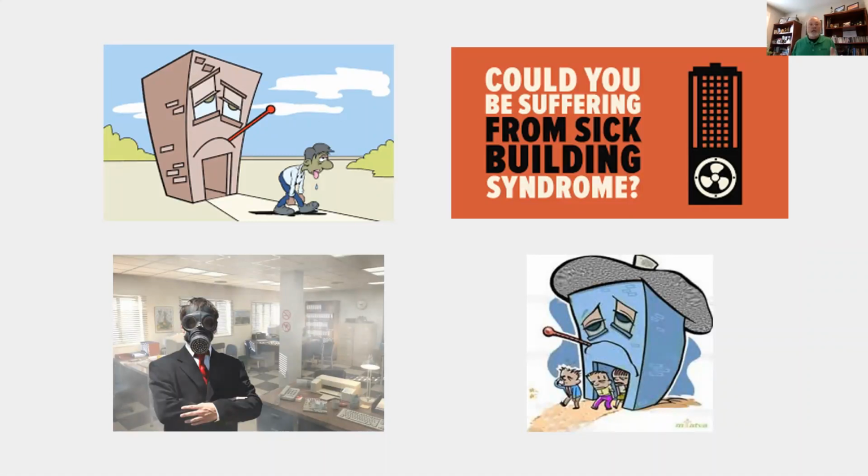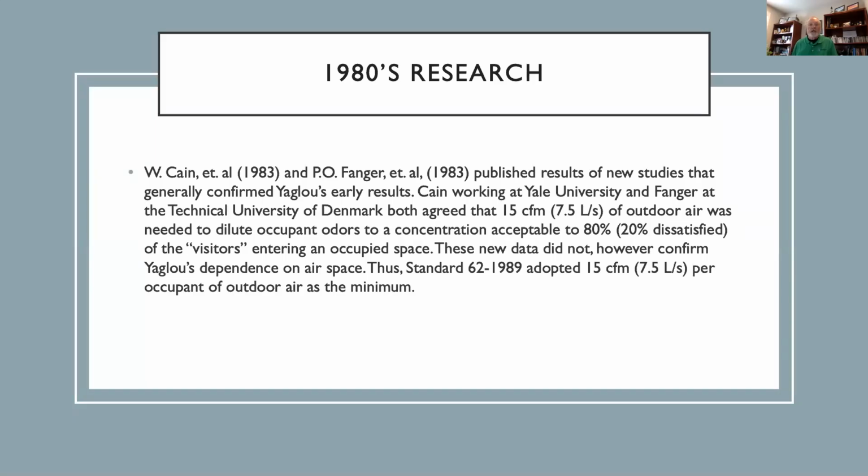Well, ASHRAE said, oh, gee. There were lots of conferences on indoor air quality, lots of conferences and papers at ASHRAE, lots of discussion. And there was research in the 1980s that said, yeah, we really need this 15 CFM of outdoor air for occupant odors and acceptability. And it also then looked at what happens with health. And so that was all a consideration.